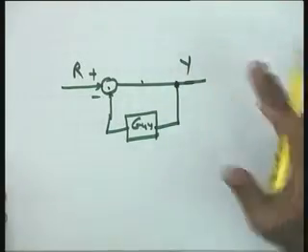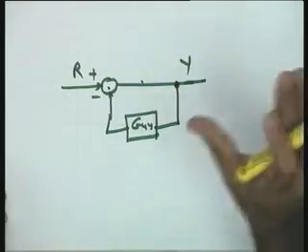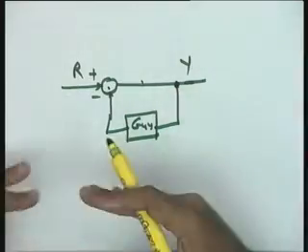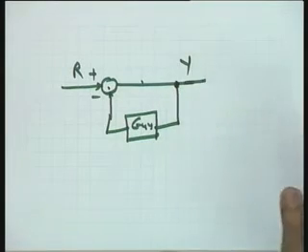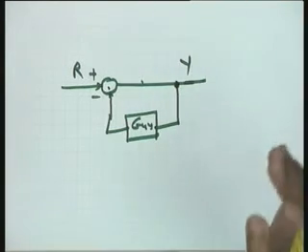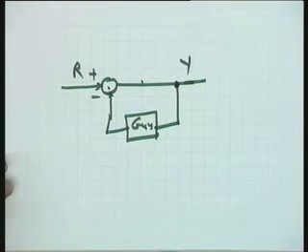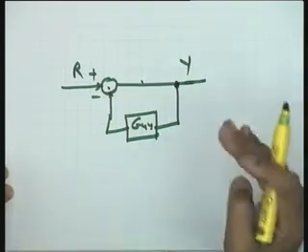But yes, the particular signal flow graph was given to you so that non-touching pairs are available and you are able to get the delta in a bigger way, that is, at least the second bracket should become applicable, otherwise the earlier example terminated at the first bracket itself. That was the very specific objective. I hope this is okay.